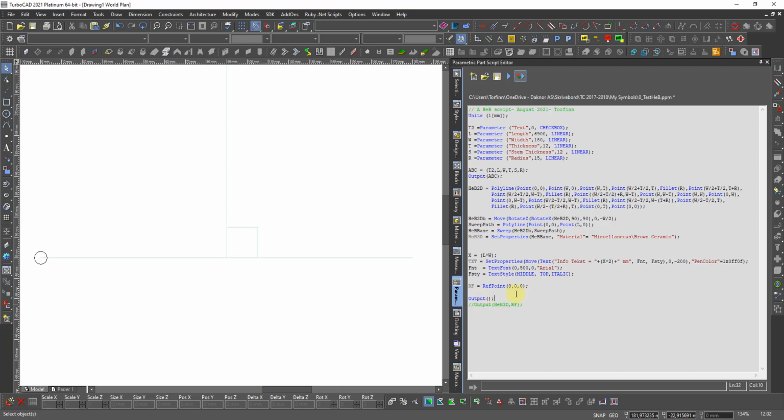Like I say, I like to use this semicolon. We don't need it, but it's very good. Space, and then we can make arc. If you like, yes. That is then a polyline.